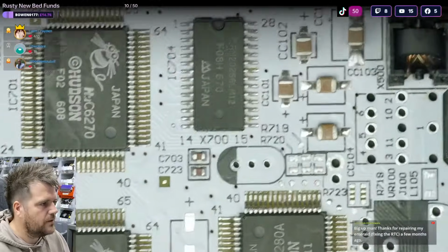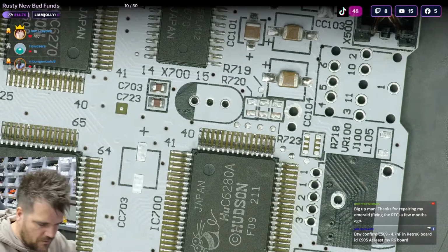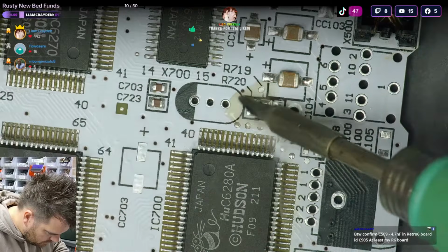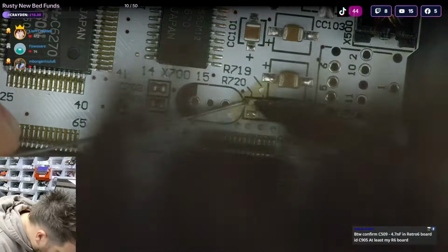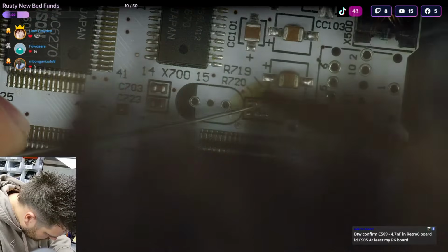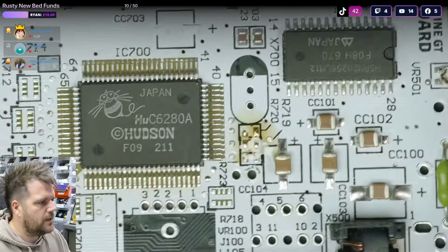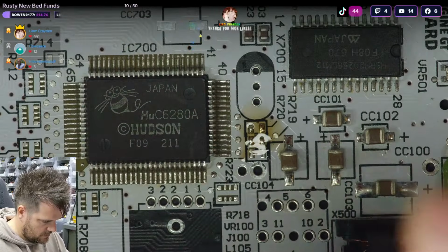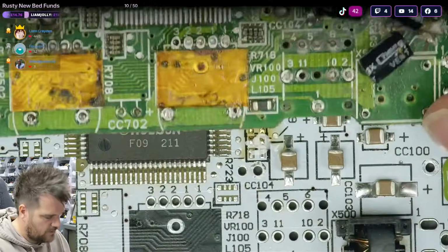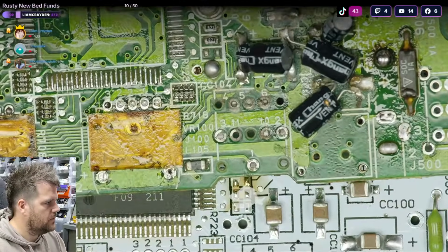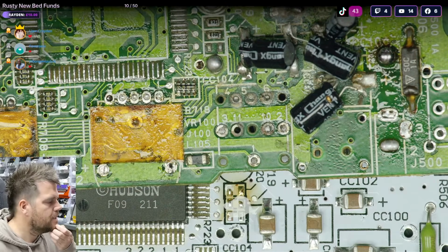And then all we have to do is prepare these pads here with flux and solder. And again, let's try not to put too much solder on the pads because the resistors are coming off the other board with a little bit of solder already on them, and they end up bubbling up. So tiny bit on there. We'll put that way, get this board that way. There we go. And then we'll just hot air them off. So I don't know whether you can see both just about there. Just about fitting both in frame.